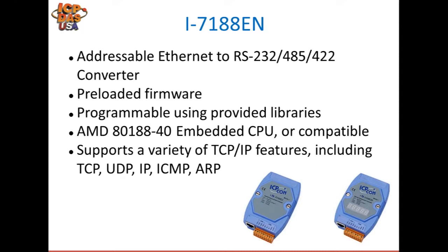So for instance, for Modbus networks, if you had multiple masters and wanted to connect to the slave devices, you could, because the TCP connection allows for multiple connections. The communication to the Modbus RTU devices will be buffered and will be passed along sequentially based on the firmware.